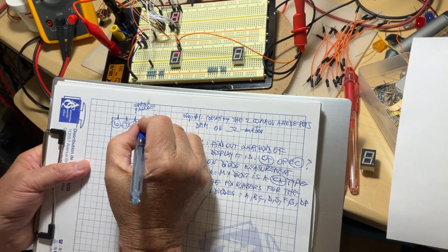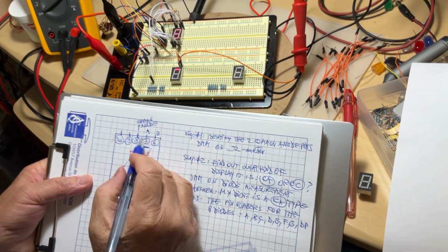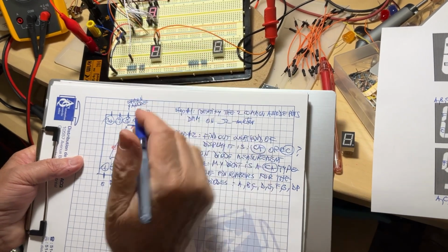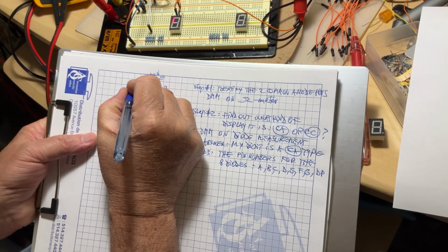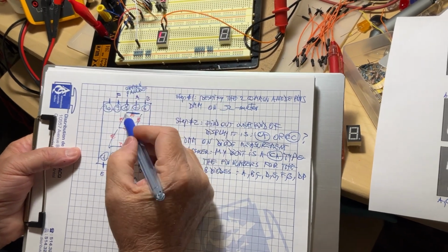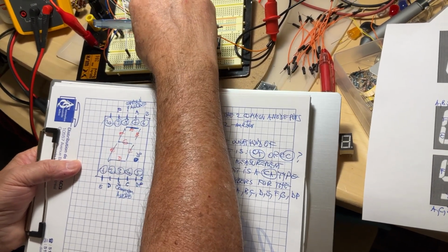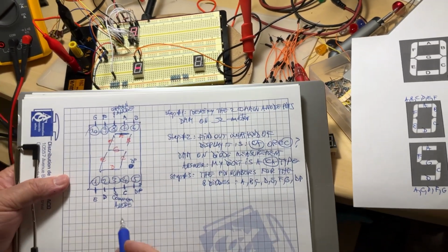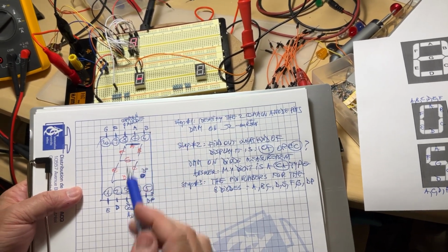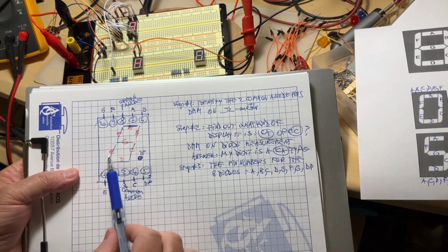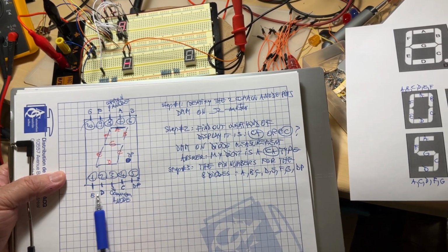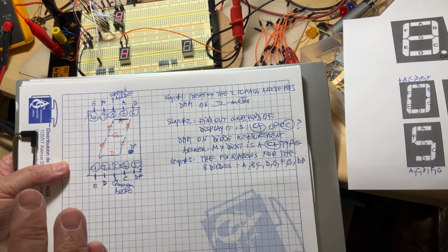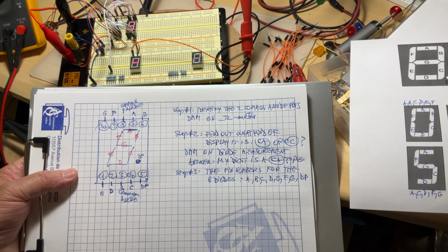On the pin 7, I have the segment A. I pass over the pin 8 because pin 8 is the common. I go on 9. Oh, 9 is the F. Why the F? Because this segment here is F. And last one, no other choice, is G. So you see, it's like I never saw that package before. And now I identified what segment is connected to what terminal of the whole package. I didn't even need the paper sheet representing the documentation of this package.